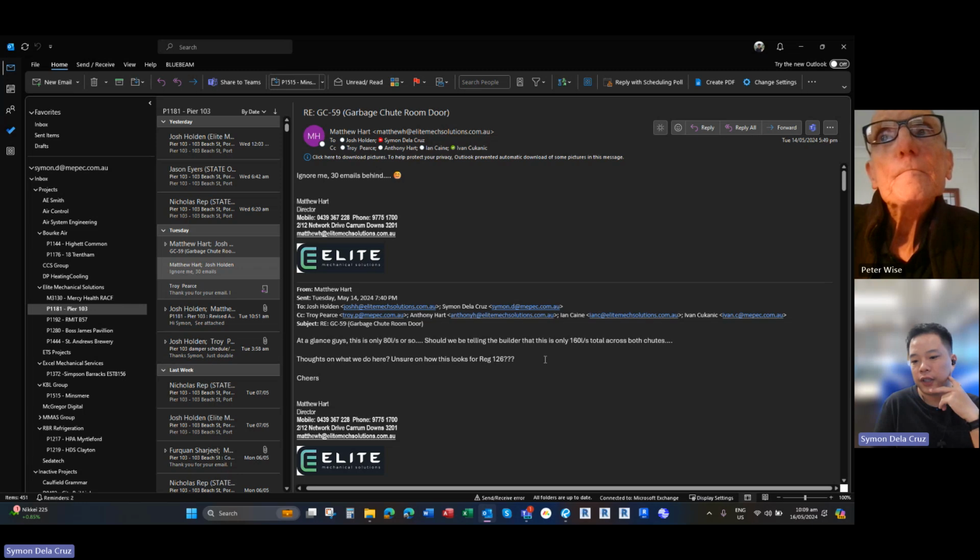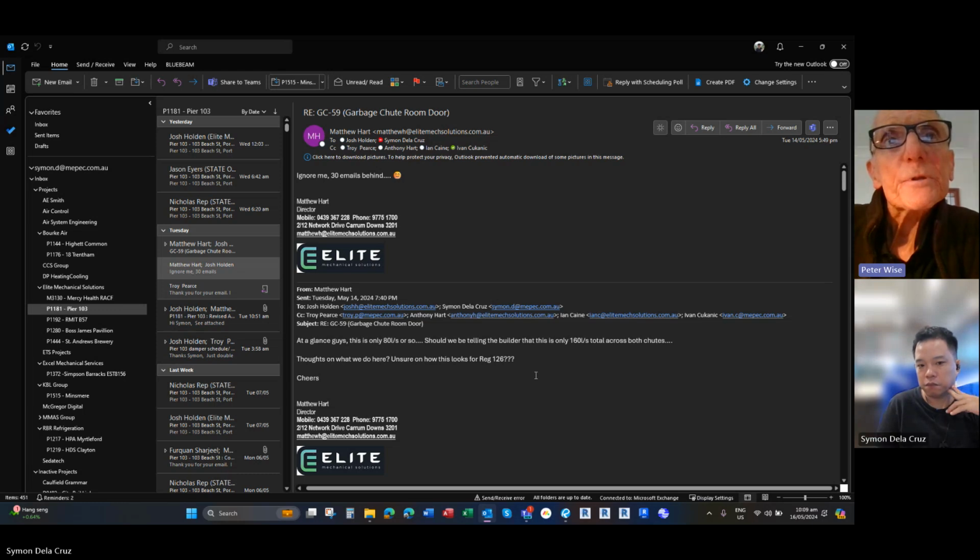No, they haven't yet provided. They might just tell us to provide the airflow, and the consultant will check it. So we are just waiting. Each fan, you've got two separate shafts, each fan is 100 litres a second, assuming that there's only one chute open at any time.